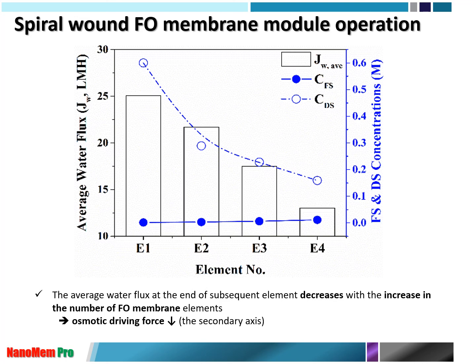What's the average water flux when you use the osmotic pressure of seawater and wastewater? You produce around 25 LMH, with the first element, second element, and last element around 12.5 LMH water flux, which is the optimized condition of our overall average flux, giving a better operation.